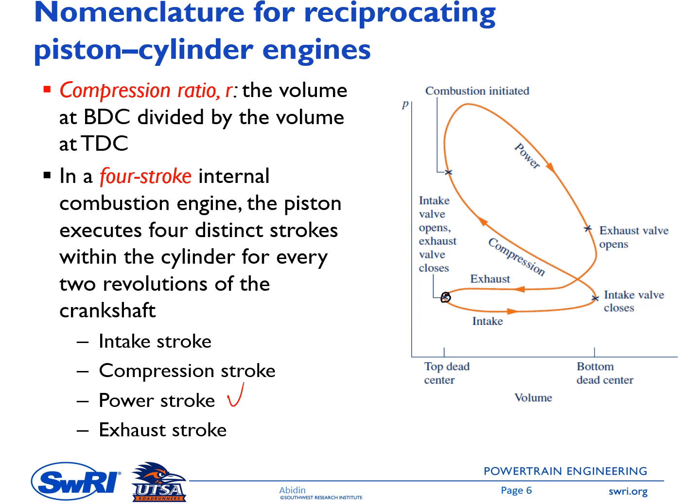In this ideal process, the intake valve opens when the piston is at top dead center, and the exhaust valve closes. So the intake valve opens and then the piston moves down toward bottom dead center. Therefore, the cylinder chamber volume increases. It's going to the right here. See here, this is the volume.